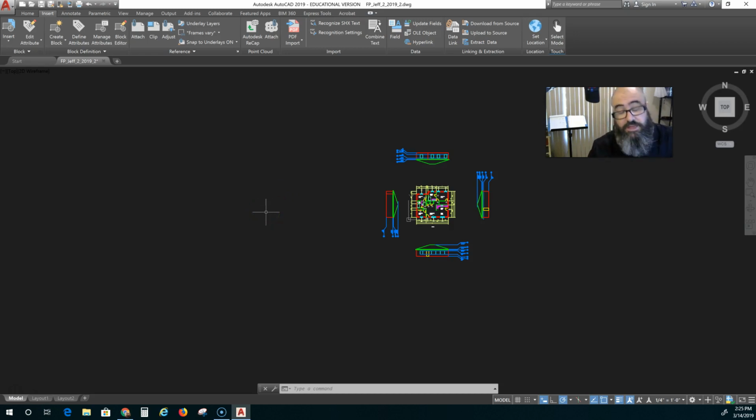They can get pretty complicated, not just in all the information that is included on one, but also in the way that you do it in AutoCAD. There's many ways of doing it. There are certain ways that you can do it where you can save that block and be able to use it across all of your drawings. But this one's not going to show you that. It's going to basically show you how to create a block in the drawing that you're currently working on.